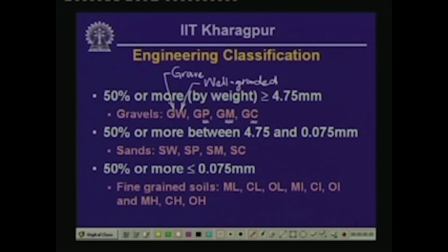So, what may come to your mind is, what is the difference essentially between a soil classified as GW and a soil classified as GM, because both of them include a large range of particle size. Now, the difference is that GW is used to denote a soil that is free from finer grained particles.